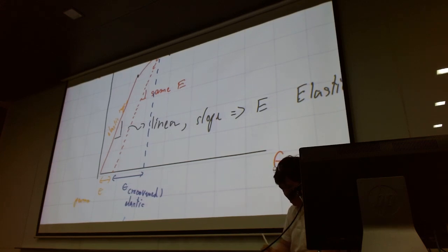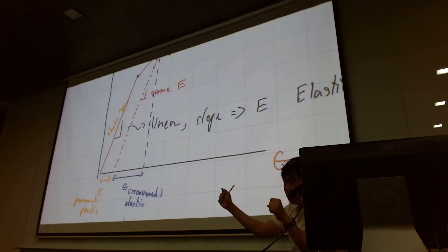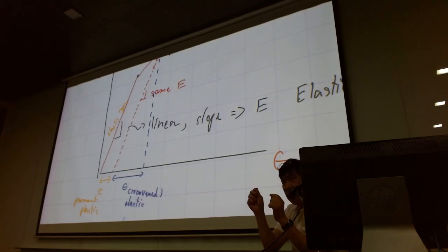This is permanent, or we call it plastic strain. That means after a while, the deformation becomes permanent. So if you have, for example, a paper clip, you bend it a little, it comes back to the original shape, but you bend it to a certain point, your paper clip will deform. That deformation is what we call a permanent deformation or plastic deformation of the metal itself.